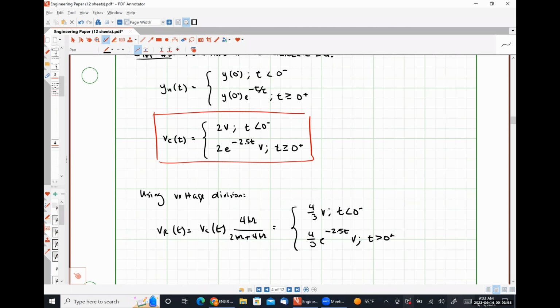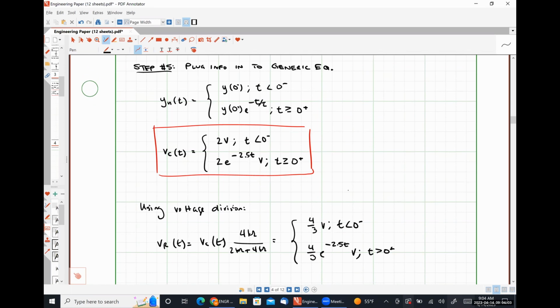We get literally the exact same result if we plug in values into our generic equation. Now, there's no need for us to actually do that circuit analysis that I did there, even though it was trivial as doing voltage division. If we keep track of all of the pieces of information at the different points in time, we can use that generic equation, even though we derived it only for capacitor voltages and inductor currents, for literally any voltage or current in our system, because KCL and KVL have to be true, right?